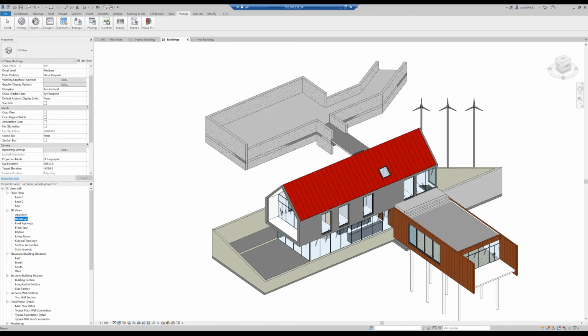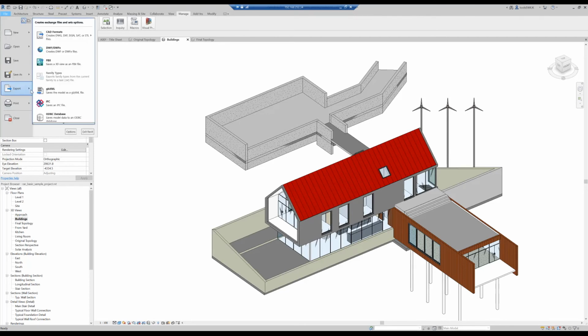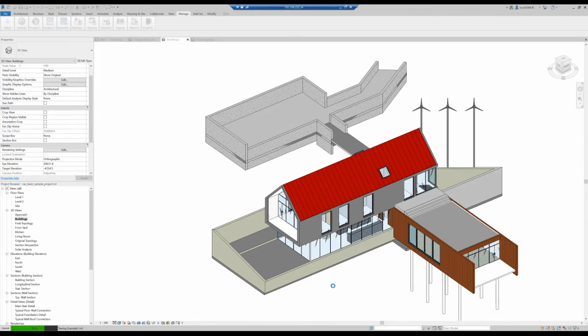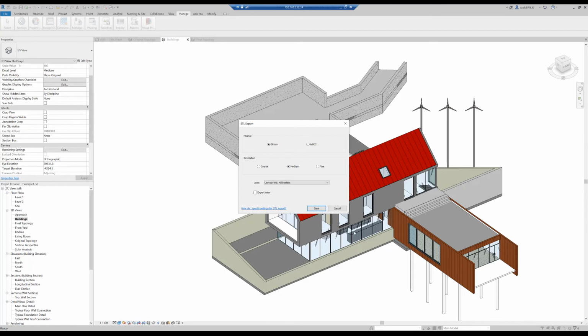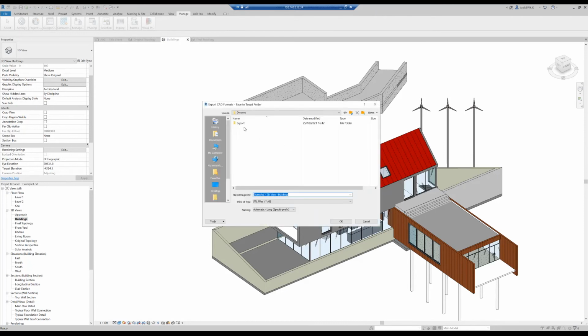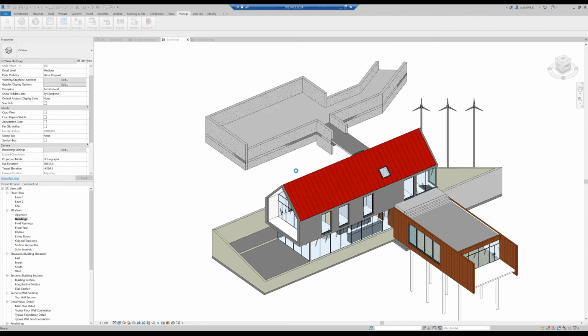And I'll show you once again how to do that. Go File, we'll Export, CAD Formats, and STLs. So we can select the defaults. This time we choose meters again, and we save that. And when we go into export, we want to export as buildings.stl. And we can overwrite our previous one. And there we go. We have now created both of the layers.